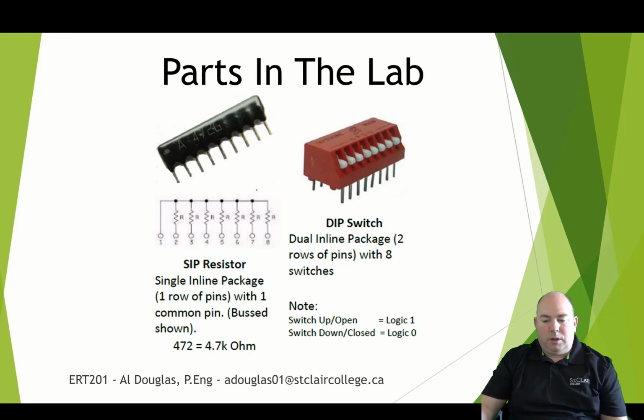Other things we use. If we were doing live labs, we would be using the SIP resistor. So single inline package is what SIP stands for. This is basically a package of 7 resistors built into one little package that fits nicely on a breadboard. So we use this in combination with the dip switch a lot.